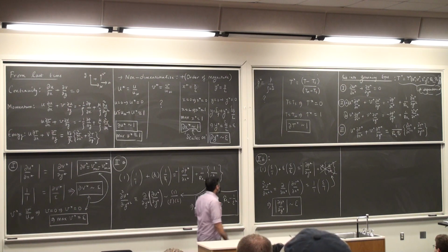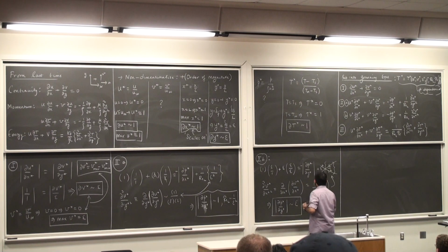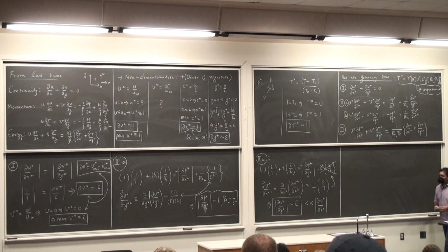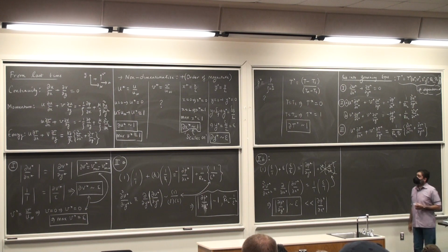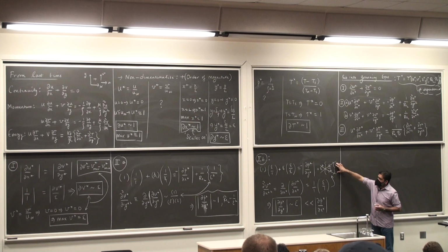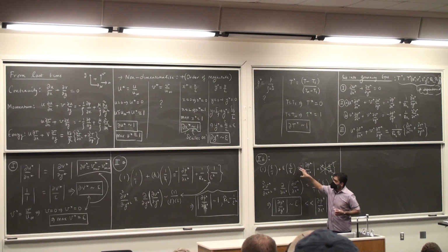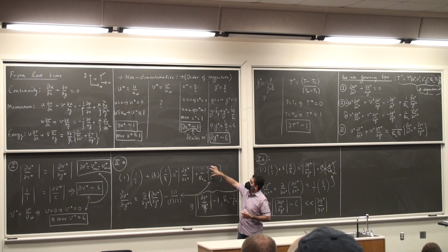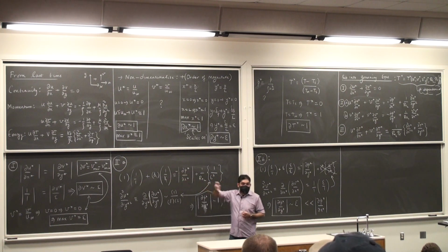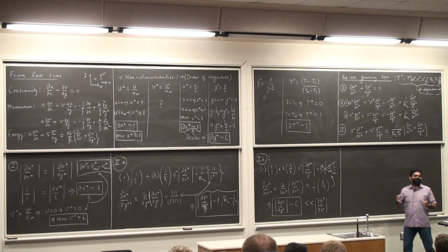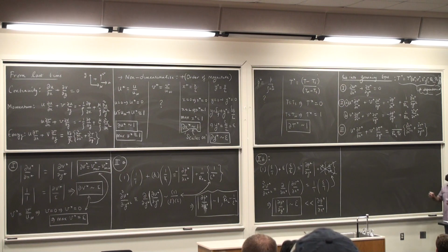Okay, so from this we conclude this is much smaller than dp star by dx star. And we also say the following: equation 2b, at the minimum each and every term scales as epsilon. Equation 2a, at the minimum each and every term scales as 1. So equation 2b is not as dominant in the scheme of things compared to equation 2a. So I'm going to cut off that equation.